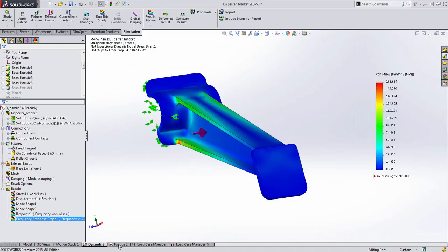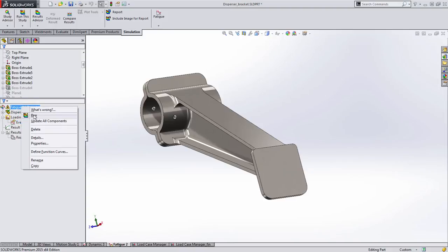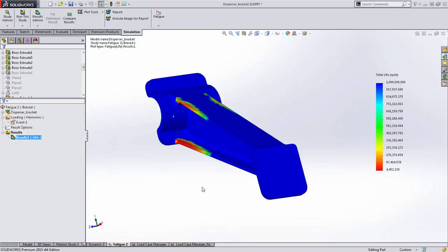And then obviously the concept of supporting dynamic fatigue loads now from either harmonic or random vibration, and you can either mention that you can come in and pick a particular frequency, or you can do multiple blocks to look at damage accumulation from repeated cycles at different frequencies. That's up to you. Obviously this doesn't take very long to run, so it's pretty quick and easy to show the data.